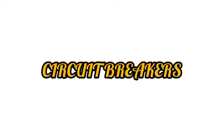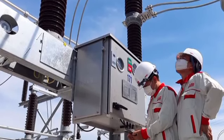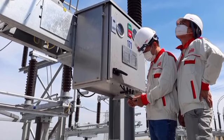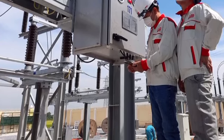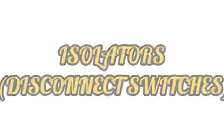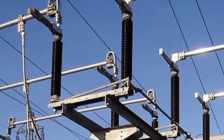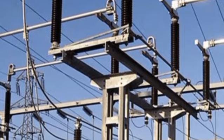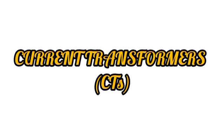Circuit breakers. Type: SF6 gas insulated, or vacuum for lower voltage parts. Function: interrupt fault currents during abnormal conditions, installed on incoming and outgoing feeders and transformer bays. Isolators, disconnect switches. Used for no-load isolation of equipment, available in single or double break design, may include an earth switch for safety during maintenance. Current transformers, CTs.